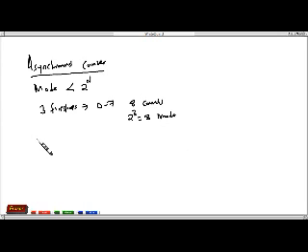So it's a mod 8 or a mod 2 power 3. At times, we don't want to count all the different numbers between 0 and 2 power n. For example, if we want to design a counter that counts from 0 to 4, a 4 is 1, 0, 0. Notice in this case, we would still require 3 flip-flops because 4 has 3 bits, just like 7, which is 1, 1, 1. And in this case, we will not be utilizing all the counts.